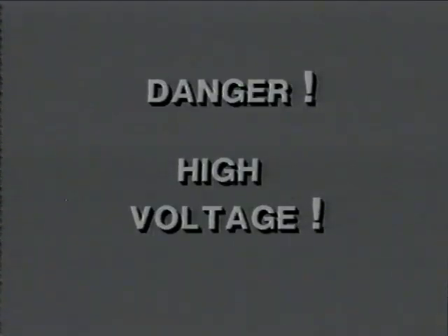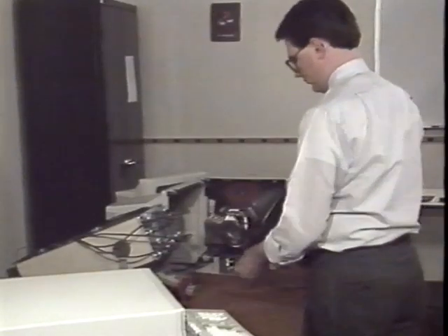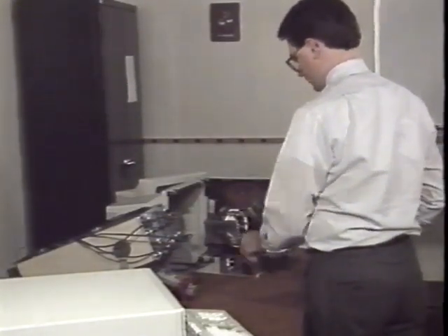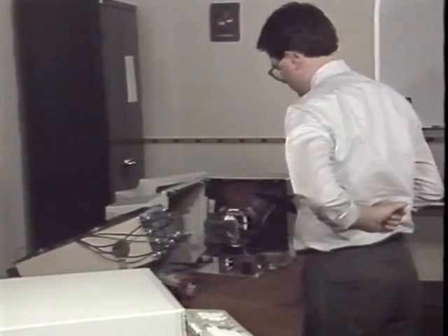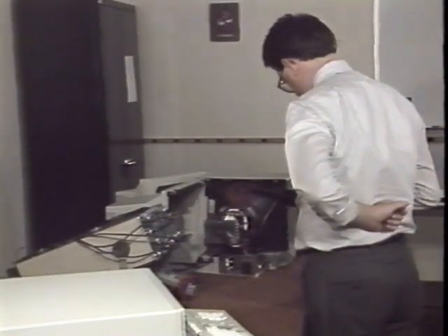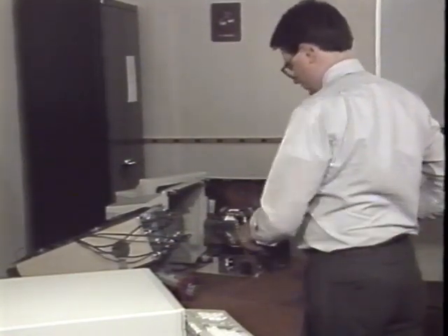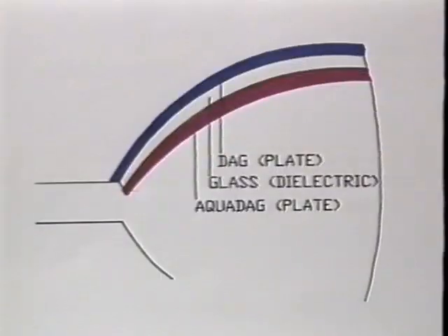Finally, you must exercise caution when handling CRTs due to the high voltages present on it. Remove any jewelry before servicing a CRT to prevent accidental contact with the high voltage points. Be careful not to touch the anode or anode lead. For maximum safety during service, keep one hand in your pocket or behind your back to avoid completing a current path through your body. Even when the CRT is not installed in a monitor, it still presents a shock hazard.